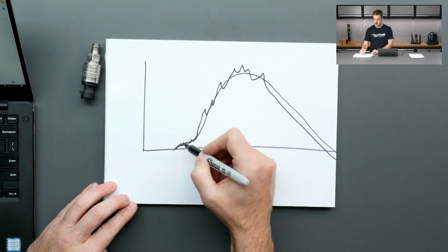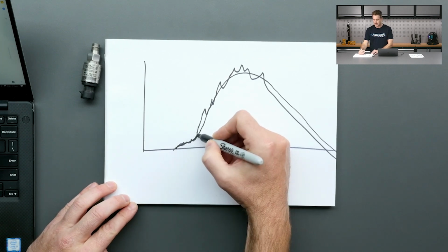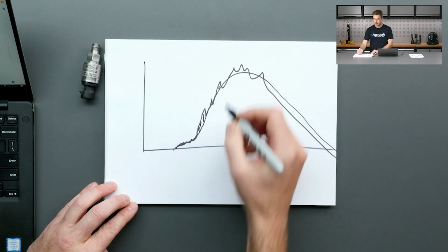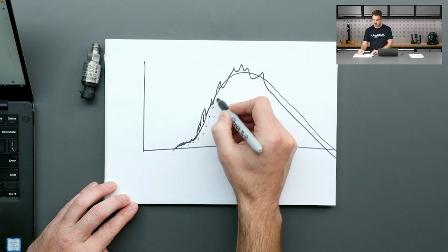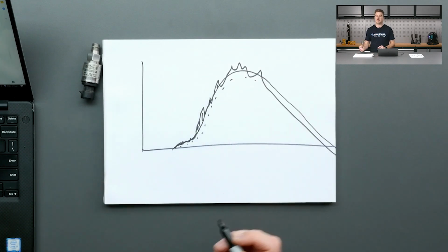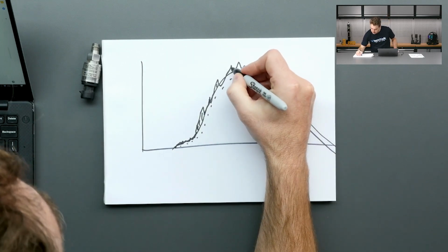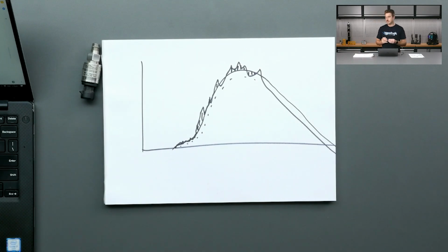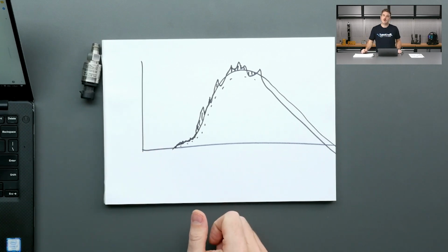Then after that, we're writing a math channel where at each time step we want to find the difference between the smoothed and raw channels. Obviously each one of these is a discrete time step that you're measuring at. So at each time step, you take the vertical difference, and you look at the absolute value, because you don't care whether it's above or below the smooth line. You care about whether there's a difference. So you'd be looking at this one, this one, this one, and so on. The idea is that you sum up the amount of difference over a lap, and the difference between the smooth and the non-smooth gives you a smoothness calculation on your brake pressure.